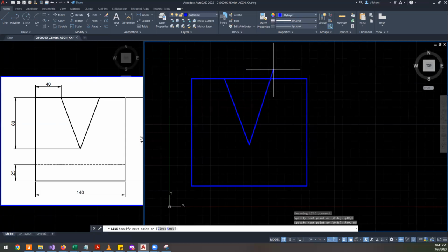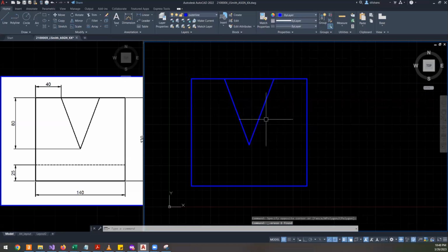So that is okay, I would say, but you are spending commands unnecessarily. Then I can type like @30,-80, and you will come to this position, and then later you can delete this line, or what you call erase. Yes, you can do that, but it is not the best way, I would say.